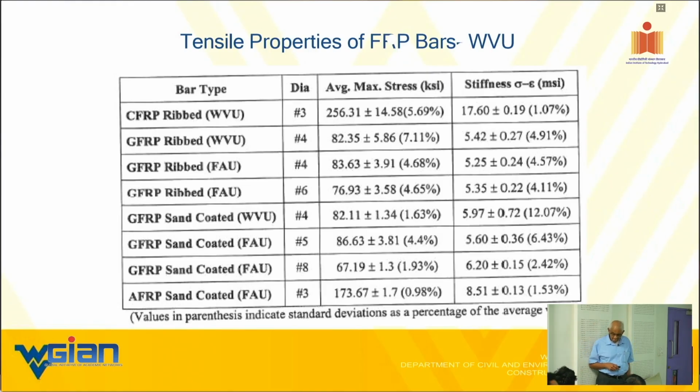One more thing, sir. Like you were saying that the fatigue life of FRP reinforced members is more than that of steel reinforced members. So how is that? But as we know, the area under the stress strain curve of steel is more than that of FRP bars. I am comparing up to the yield point. I'm not comparing the area beyond the initial formation of the plateau, because when we are talking about fatigue, we do not operate in the yield zone.